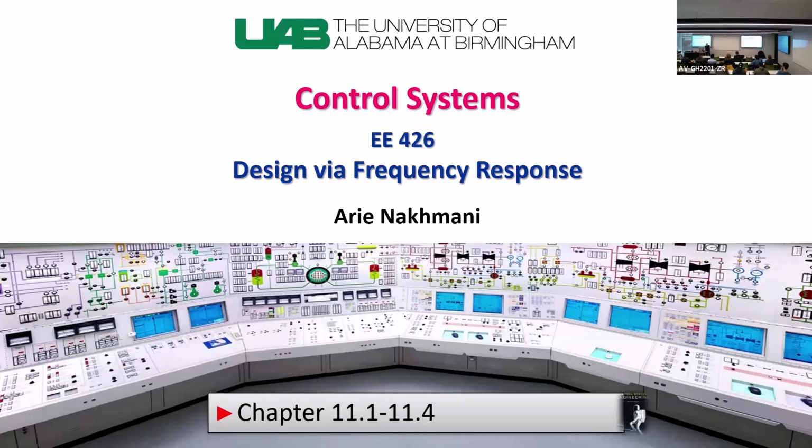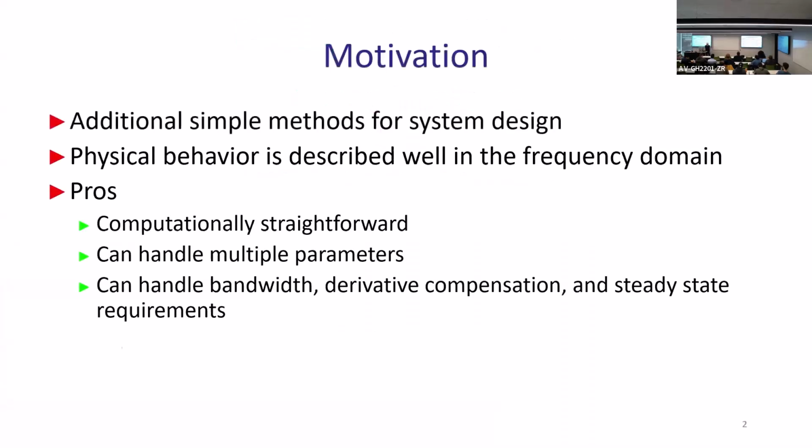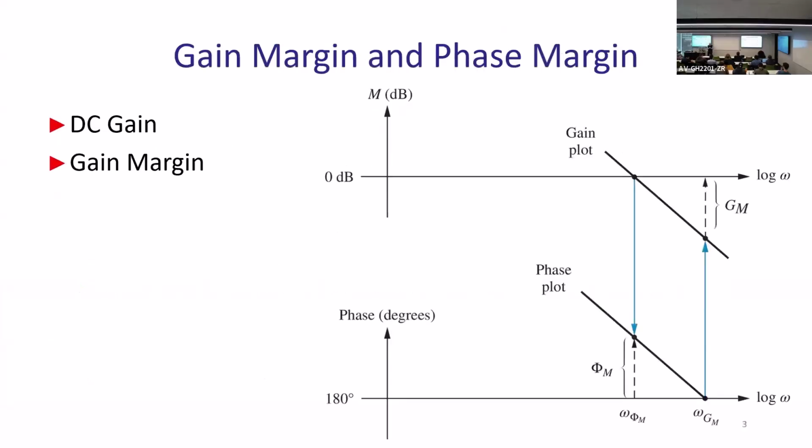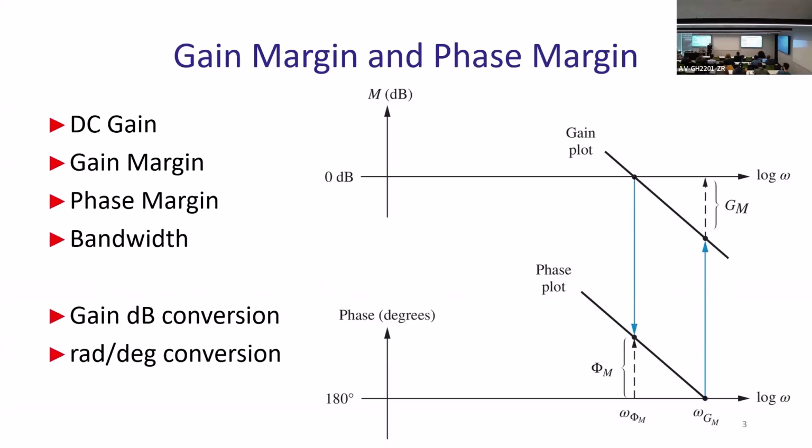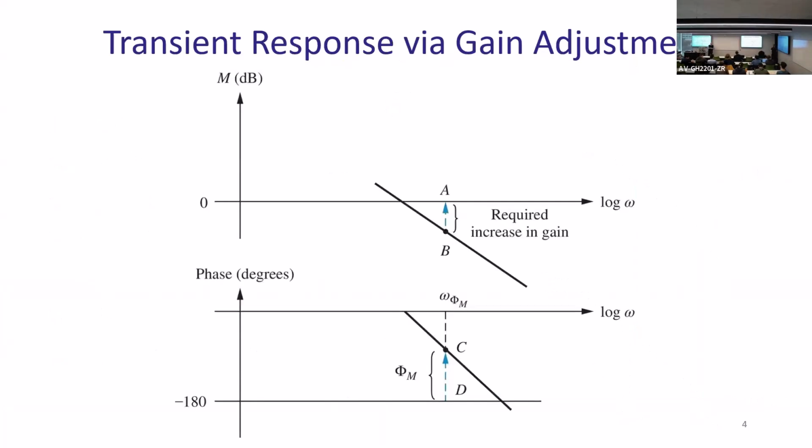The previous time, the idea was that you want to design particular phase margin in the system, okay? So given that phase margin, you want that your system will perform particular things like overshoot, having settling time, having steady state error, whatever you want. And the idea was that let's not touch the phase plot at all. This was the original idea. Let's not touch phase plot at all.